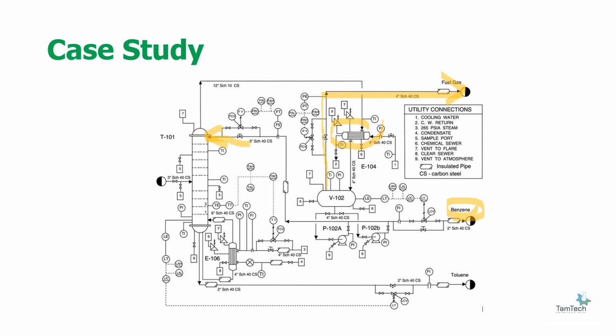If you remember how we were controlling the pressure, you could answer the question in 3 ways. The first one was flow variation, which could be done if you have a pressure control valve on this line. The second one is the flooded condenser. If your condenser is already a total condenser, you could use this method. The third method was coolant flow rate control. If you have a cooling water flow rate control valve on this line, you could also regulate and control the condenser pressure in the distillation column.